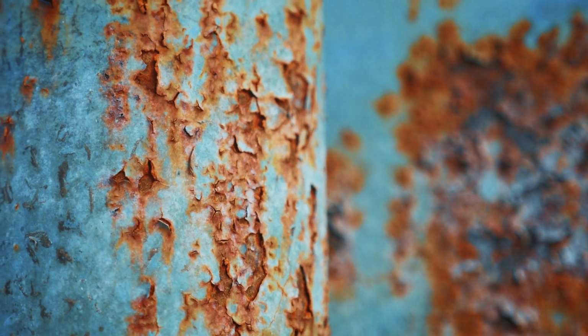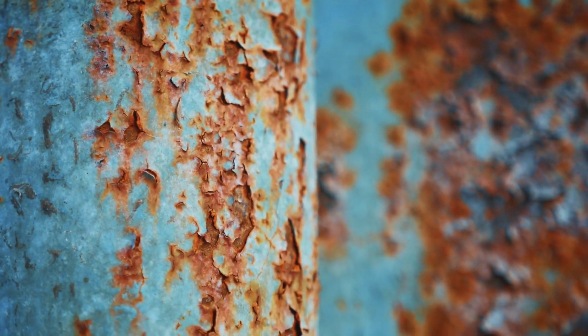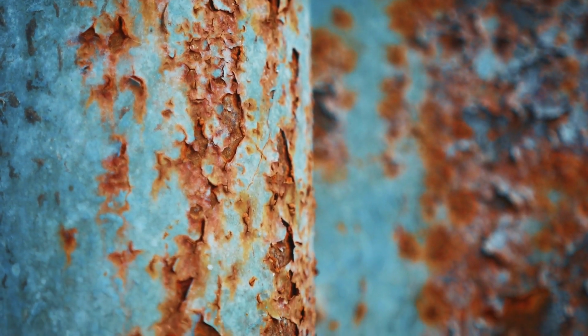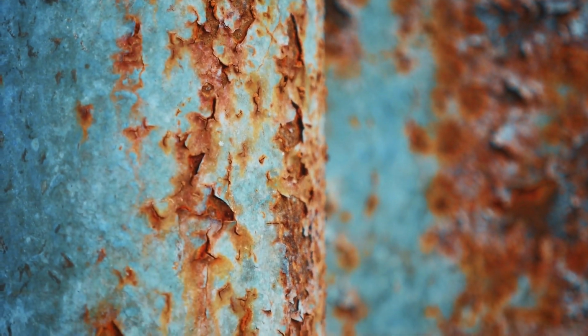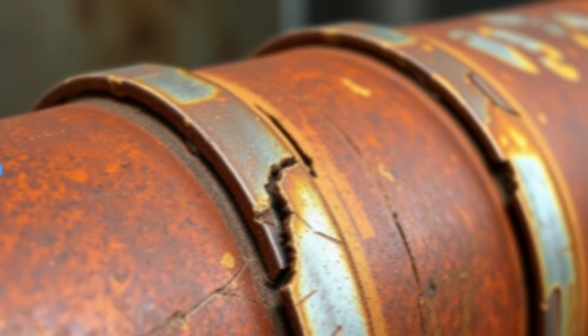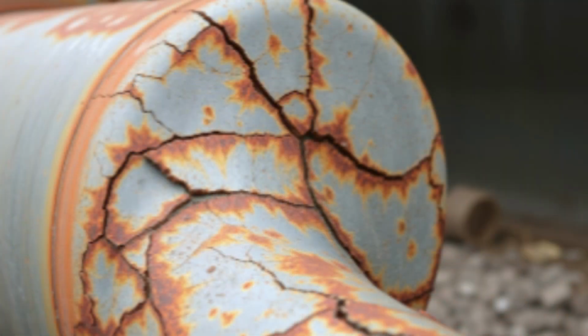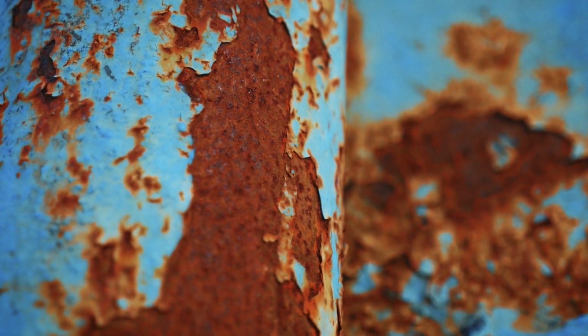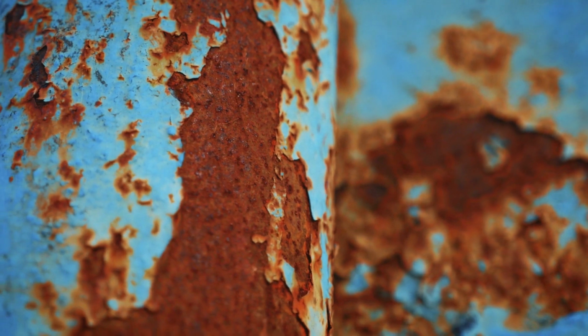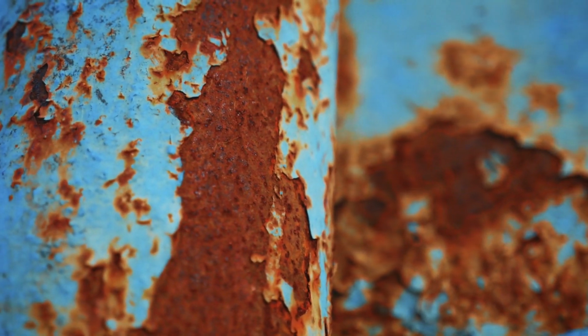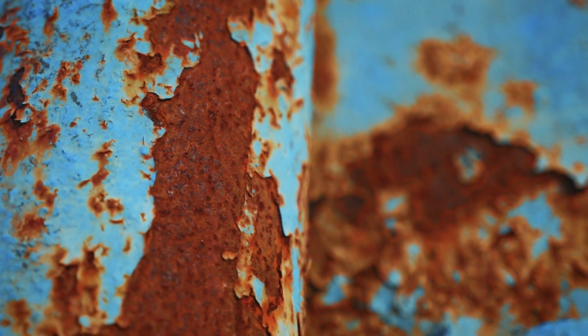Appearance. Corrosive stress often manifests as fine, branching cracks or pits on the material's surface, particularly in areas under mechanical stress. These cracks typically begin as small surface flaws but deepen over time, creating branching patterns and leading to brittleness. The material may show visible signs of corrosion, such as rust, discoloration, or surface roughness. In severe cases, these cracks propagate quickly and can lead to sudden, brittle failure without much warning.